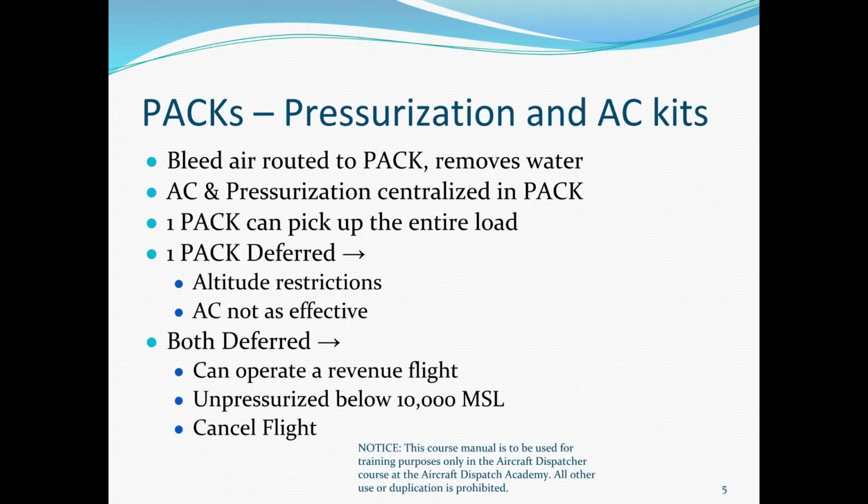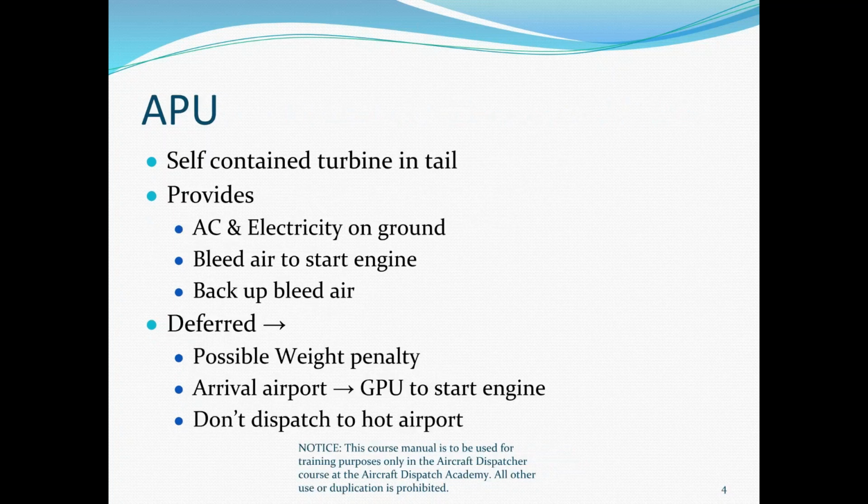So that's the issues with the APU, and I'd write down, if it's deferred, what are the problems? Remember, weight penalty, need a GPU to start the engine, and you don't want to go to a hot airport for a couple different reasons. Number one's just the performance hit, but number two would definitely be the passenger comfort.